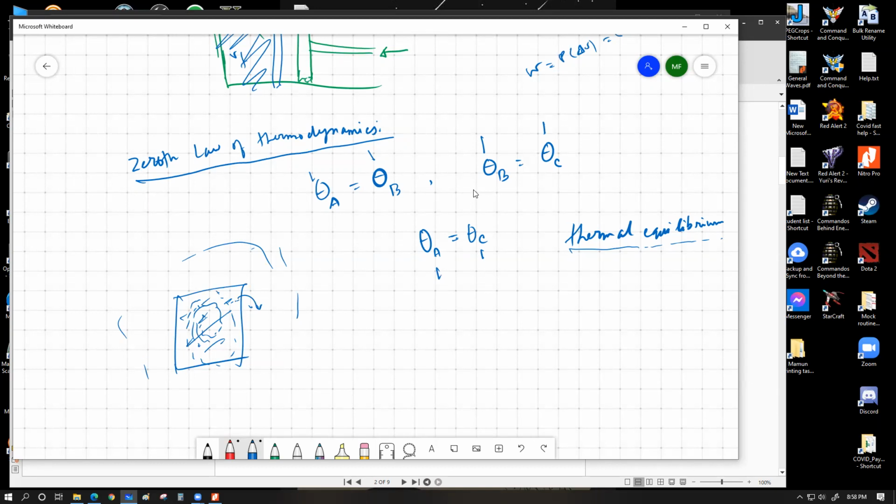In this process, the gas is made into liquid by the Joule-Thomson effect. That's another thing you don't have to know about. And eventually when the liquid refrigerant is introduced back into the refrigerator box, it is once again allowed to evaporate, and in the process of evaporating, it absorbs the latent heat of vaporization from the inside, and this cycle keeps on happening. To make this happen, we have to keep running the pump that moves the refrigerant fluid, gas or liquid, within the closed cycle.